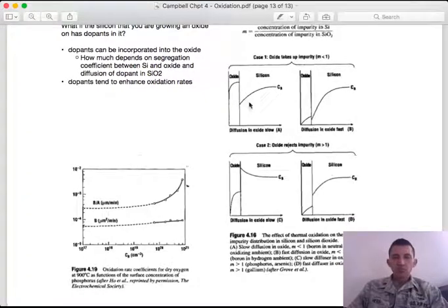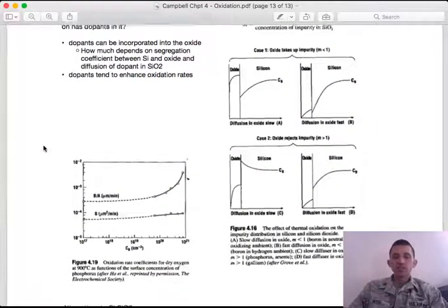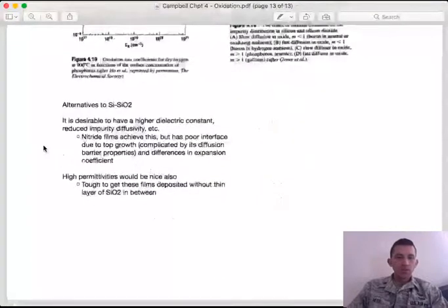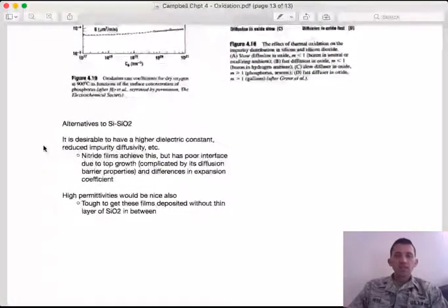But this is important because if you get this wrong, you could potentially leach out impurities from the silicon, or change the properties of the oxide layer. If you're going to leach these impurities in there, you might be making it less insulative than you had planned.